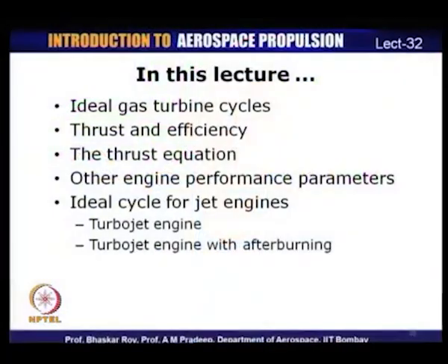So, let us take a recap of what we had discussed in this lecture. We have been discussing the ideal gas turbine cycles, and we started our lecture with discussion on the thrust and efficiency terms. We derived a generalized expression for thrust of an air breathing engine. We also defined different efficiencies like propulsion efficiency, thermal efficiency and overall efficiency.